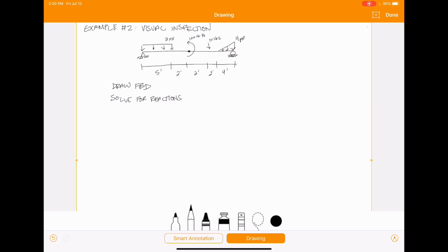So the free body diagram, in this case, start by drawing your object, apply your external forces, apply your reactions, we'll label all these different points, A, B, C, D, E, F. So this is going to be Ay, Ax, and Fy. So there's your free body diagram.